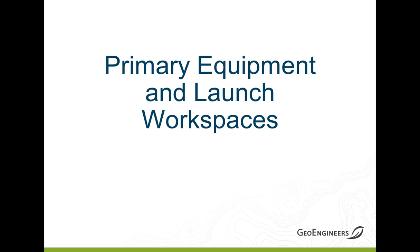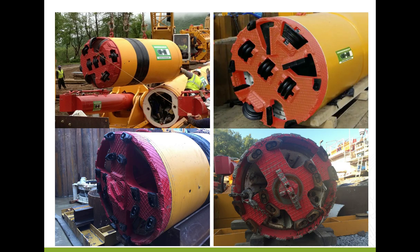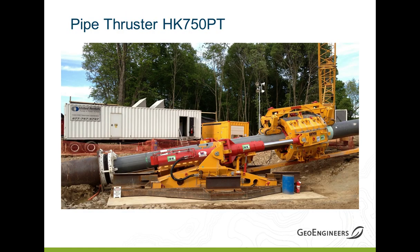Okay, so let's look at some of the equipment. And by primary equipment, I'm referring to the microtunnel boring machine and the pipe thruster machine. So let's look at some of that equipment and how it's configured in the launch workspaces. This slide shows 4 different microtunnel boring machines that were used on direct pipe projects with rock and mixed face conditions, cutting wheels in the top of the screen, and more of soil sorts of cutting wheels in the bottom of the screen.